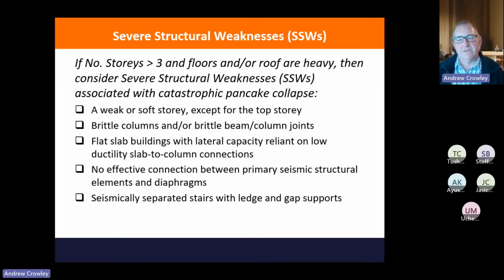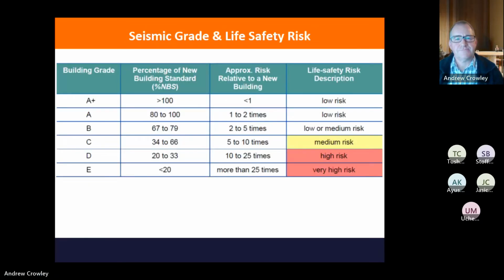Another issue with stairs, though, is sometimes the stairs are supported halfway up a masonry wall. So a seismic event will then put lateral loads out of plane on a masonry wall, which can lead to its collapse, which will lead to the collapse of the stair. If any of the above, it's a potential earthquake-prone building, and you then have to justify why it's not an earthquake-prone building.